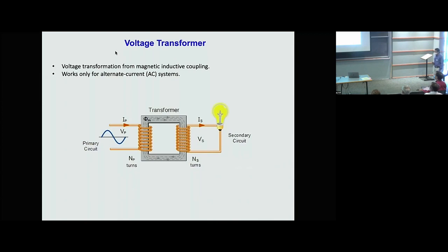This is actually extremely important in both electronic and electrical systems because it allows us to basically tailor the voltage to where you would need it. For example, you may want a high voltage for low loss transmission over long distances, but then a low voltage to drive your electrical circuits and so on. And now, the standard thing that we're used to seeing is a magnetic transformer.